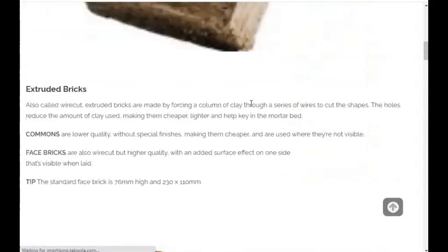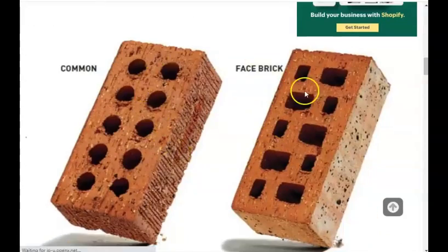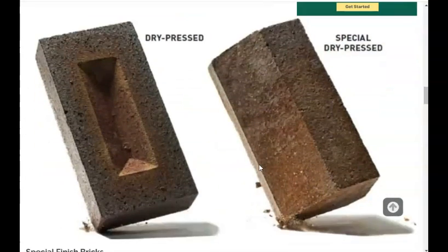Types of bricks. Okay, so this brick here is extruded. That's what's got holes. These ones here are pressed. What do we call this indent? We call it a frog. You use the frog so it holds the mortar. It keys into the mortar. My understanding is that you put the frog on the bottom of the brick when you lay bricks, unless you're in Ireland, where I heard from a student recently that it's the reverse. My dad lives in Ireland, he tells me they mostly use besser blocks. You don't see a whole lot of clay brick construction, but who knows.